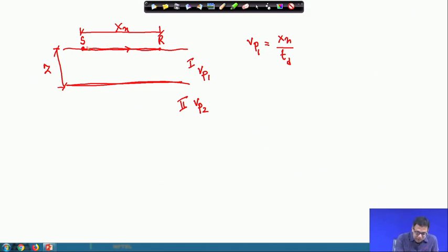Now, there is another wave. What will happen? This will come here, it will reflect, and it will be received by the geophone. Why have I considered this wave only? Because of the position of the geophone. If I change the position of the receiver or geophone, then a different wave we have to consider, but the things remain the same. Suppose this angle is I, so this angle will also be I. This is the reflected ray, so we are measuring this reflected ray.